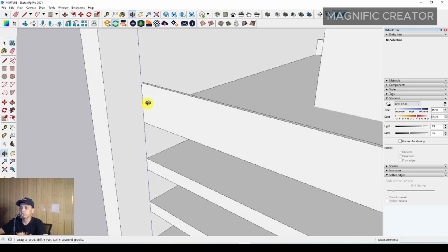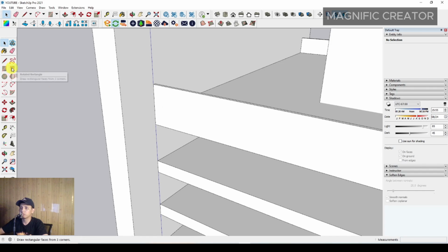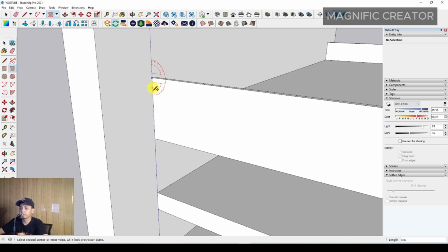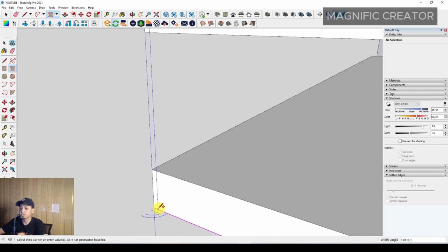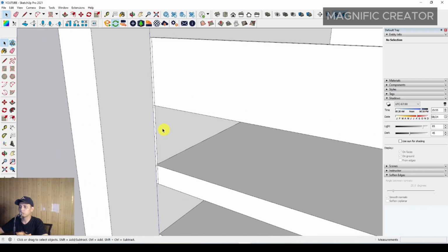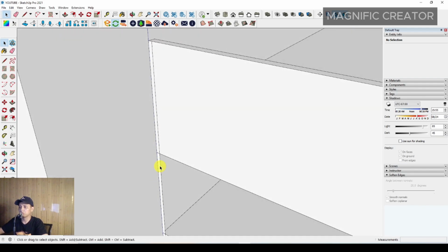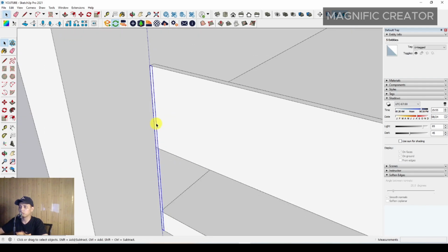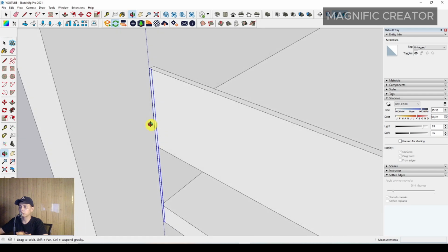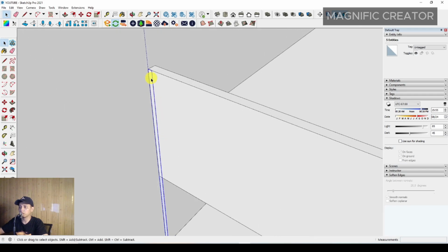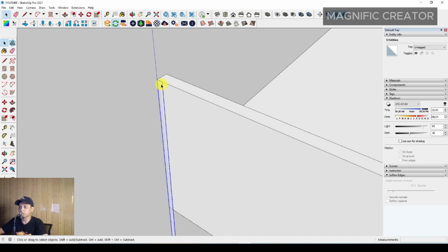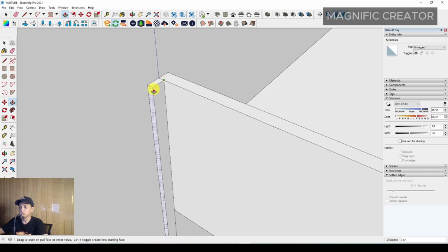Okay, and after that we have to make a frame. We have to make a curtain wall with a rectangle anyway. We can set a rotated rectangle from this parapet. Then we can make a thickness, maybe around 100 millimeter. It's just for example. For the standard dimension, you can consult and discuss with the engineering services of the curtain wall itself.